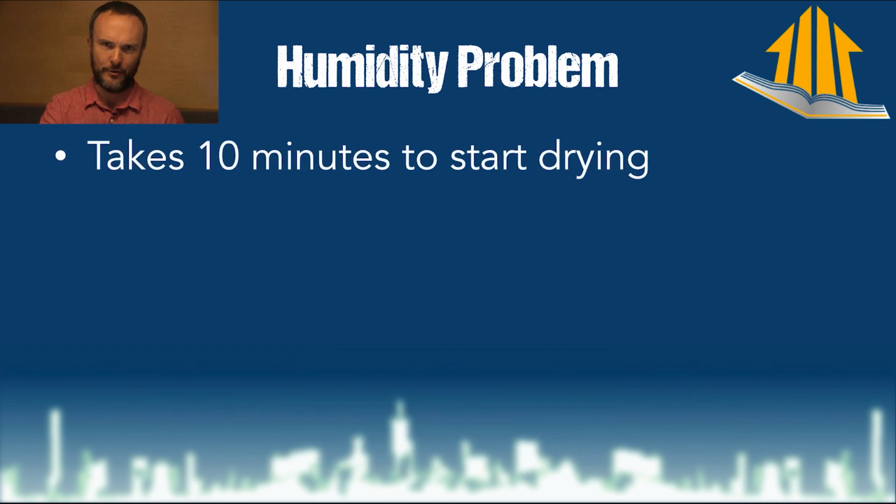The humidity issue is that an air conditioner needs about 10 minutes on average to start drying out the air. It needs to get cold enough that it's going to really start wringing out the moisture from the air and get soaking wet and then start draining that stuff to the outside. Because if the coil gets wet and then the air conditioning system turns off, what happens to all that water? It re-evaporates back into your house. And now you have done zero dehumidification.